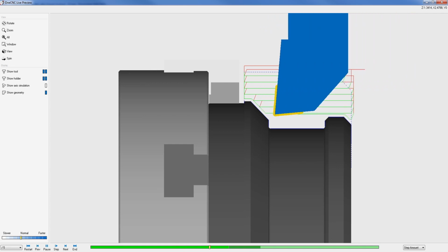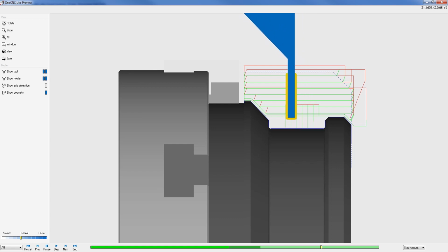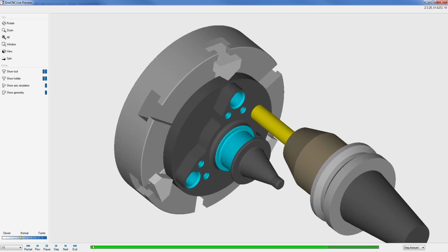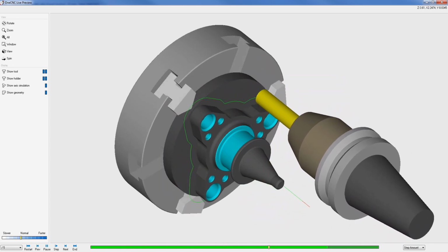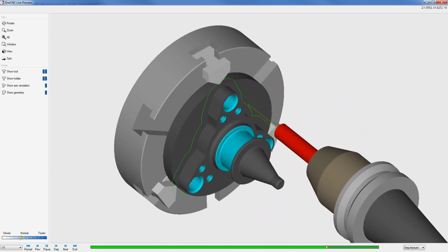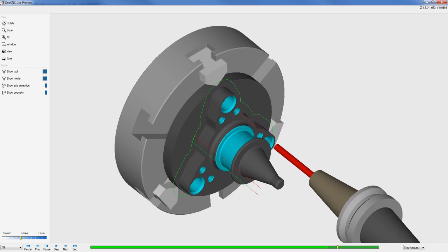OneCNC 2-axis lathe provides the ability to easily apply OD and ID toolpath to part geometry, providing efficient toolpath for rough, finish, bore, groove, thread, face, and part-off machining operations. OneCNC C-axis provides the powerful ability to incorporate live tooling to generate both radial and axial toolpaths. CNC code can be output in both polar and non-polar formats.